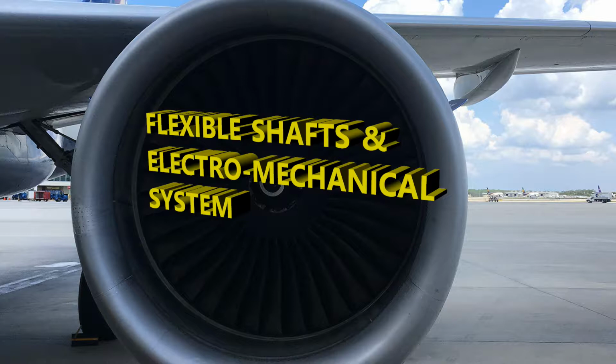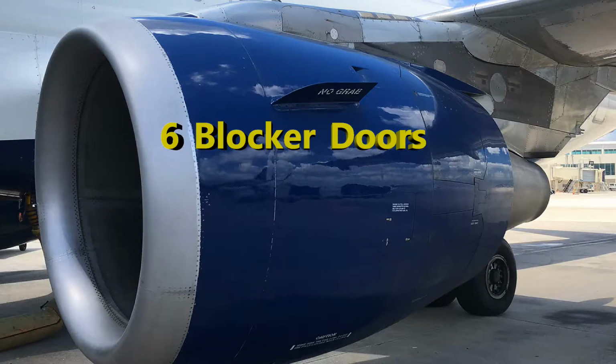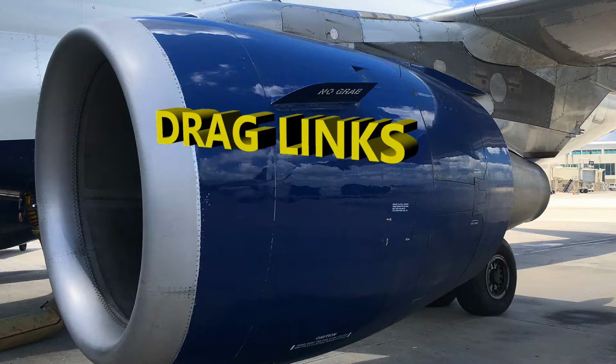And when you look at the structure itself of the cowl, what components are here? We have the blocker doors, and there are 6 of them. We covered that in a test question, but there are 6 blocker doors that are hinged to the sliding sleeve at the front end. There are also drag links that are hinged to the blocker doors at one end, and then hinged to the inner fixed structure of the cowl on the other side.